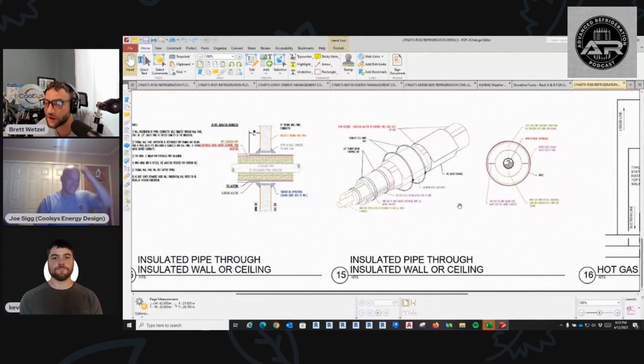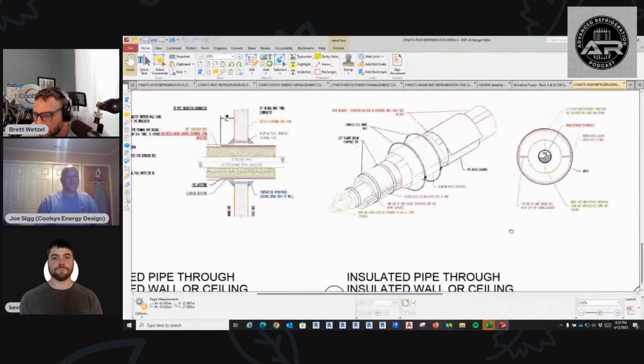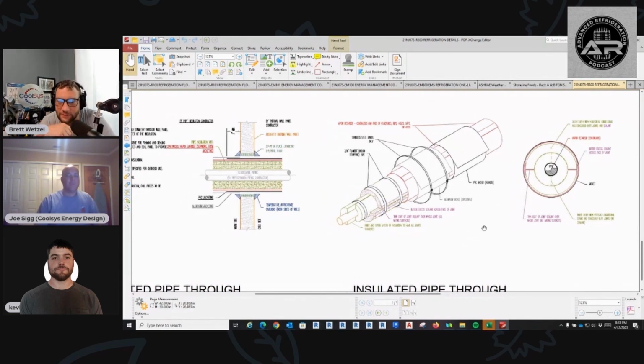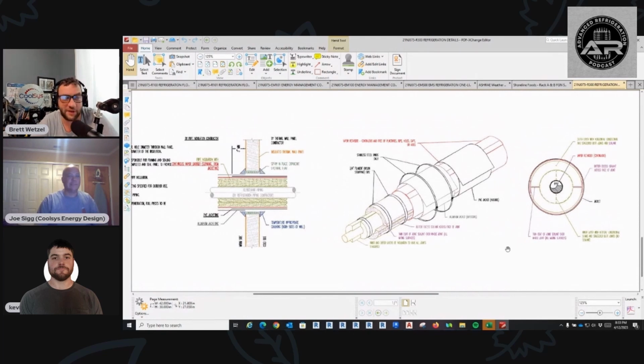All right. So are you guys doing jacketing and everything on this, right? Yes, we are. We ran all the piping on the roof of the building, and we're just popping in for each evaporator. So we double insulated it and jacketed it. It's going to cost more than the welding. Probably is, but the labor's cheaper because you can get anybody to do insulating, right? Yeah. I didn't realize, Kevin was the one that brought it up to me. He's like, "Yeah, Armaflex is just about as much as piping at this point." We're on this job. We are not using Armaflex. We're not using elastomeric. We're using polyisocyanurate.